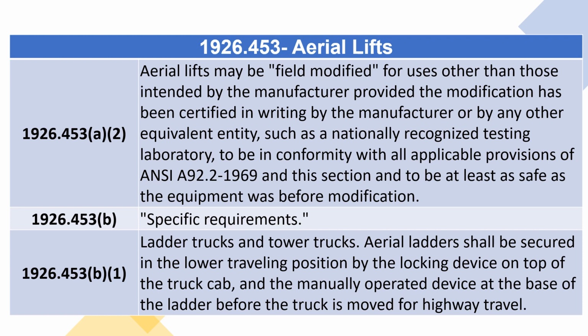1926.453(a)(2): Aerial lifts may be field modified for uses other than those intended by the manufacturer provided the modification has been certified in writing by the manufacturer or by any other equivalent entity, such as a nationally recognized testing laboratory, to be in conformity with all applicable provisions of ANSI A92.2-1969 and this section and to be at least as safe as the equipment was before modification.